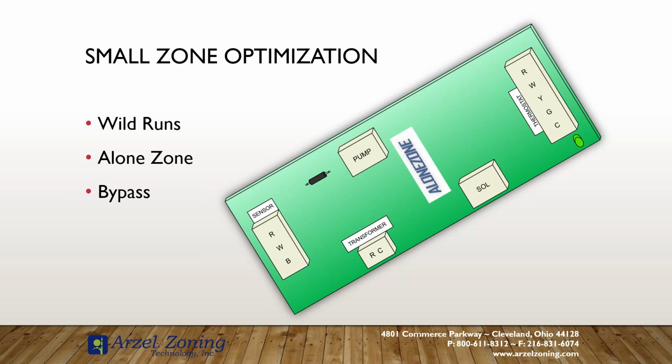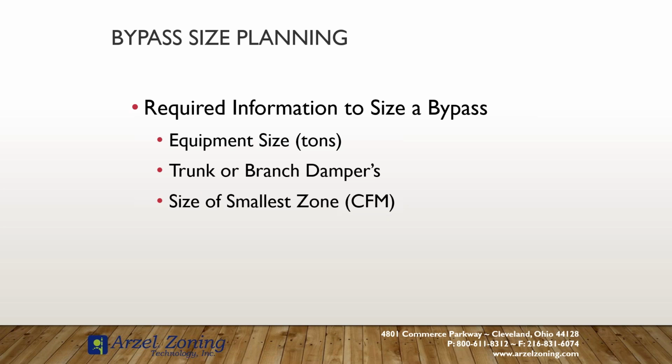And then the last option that we really look at is going to be the bypass. As long as it's designed appropriately, you're fine. But if it's way oversized, it does cause problems for the equipment. So we need to be mindful about how we're sizing the bypass duct.